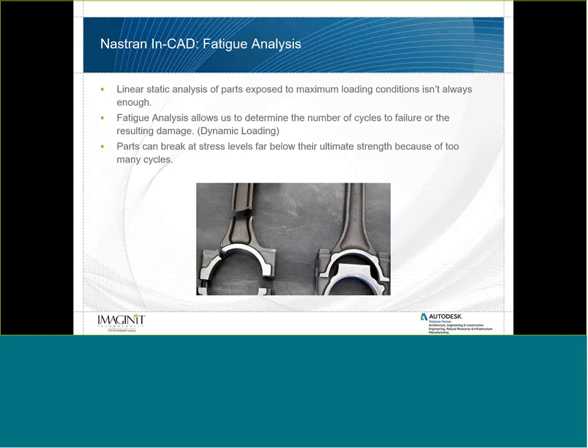We may see constant cycles being applied where the load, maybe a smaller magnitude, so maybe not even the maximum load, might be applied over and over and over again in a fashion that would cause damage, and this is called fatigue. So what we're looking at is how many cycles we can expect to achieve with our design before we start to see damage and failure as a result of fatigue.